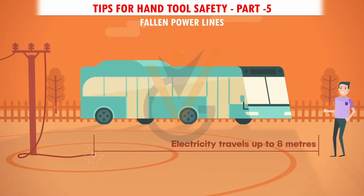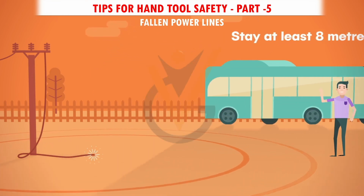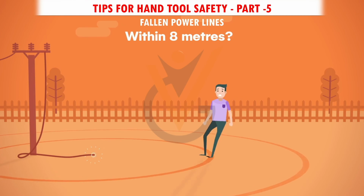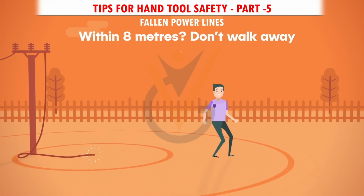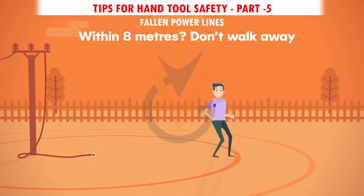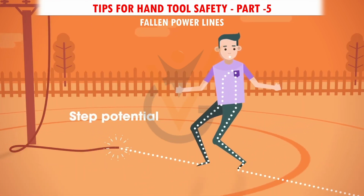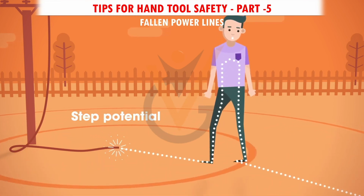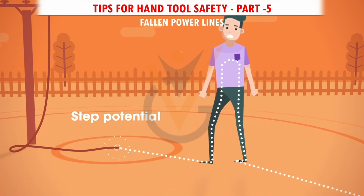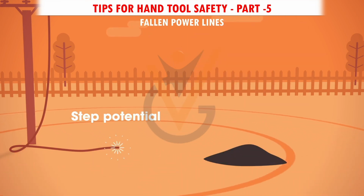Also check for any metal fences, fallen limbs, puddles or vehicles that could act as conductive materials and pose an electrical hazard. Don't touch any object or tree that is in contact with the fallen power line. Trees that are in contact with fallen power lines can be conductive. Even if you are not sure if the power line is live, avoid any contact with electrical materials that are touching the tree or surrounding it.